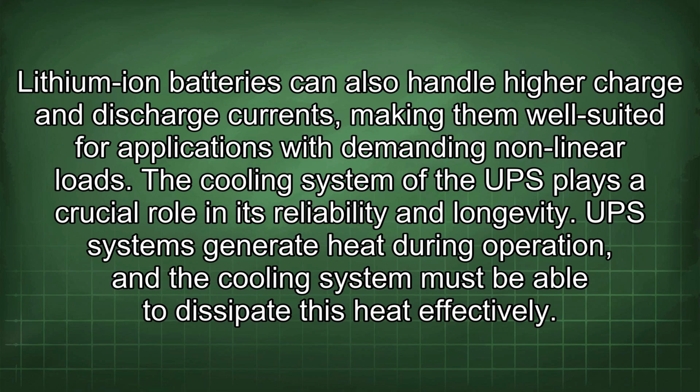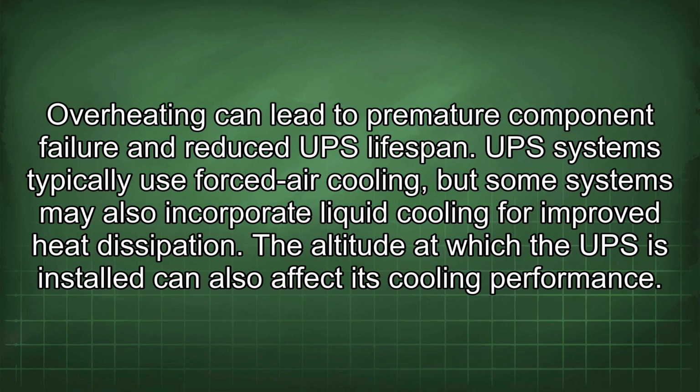The cooling system of the UPS plays a crucial role in its reliability and longevity. UPS systems generate heat during operation, and the cooling system must be able to dissipate this heat effectively. Overheating can lead to premature component failure and reduce UPS lifespan. UPS systems typically use forced air cooling, but some systems may also incorporate liquid cooling for improved heat dissipation.